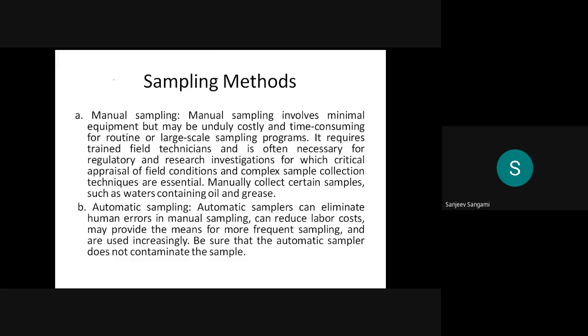Of course, we have to study each parametric analysis, how exactly the sampling has to be conducted. For example, chloride. Assume that you are going for a chloride test, how exactly should the sampling be conducted? Suppose you are doing the sampling analysis in most of the sewer network and you are interested in finding the solids, we will come back to what those solids and chlorides are, and what kind of techniques are feasible.